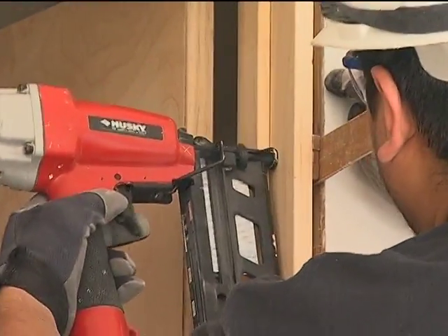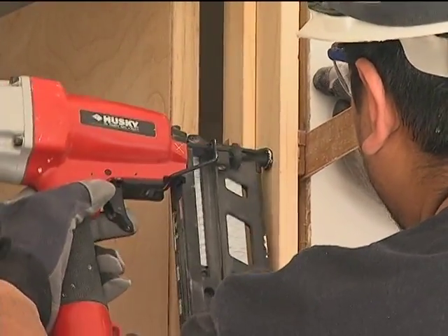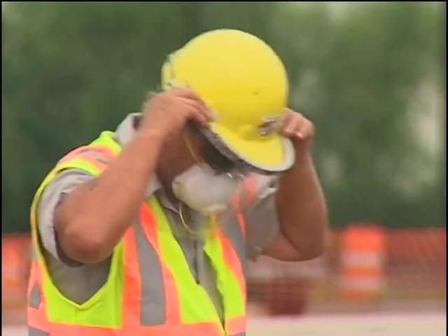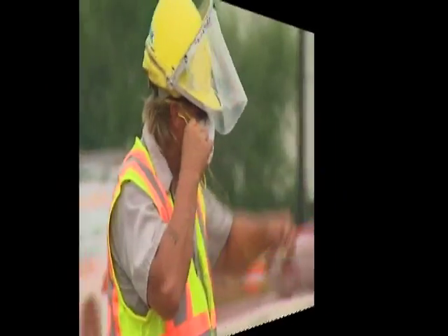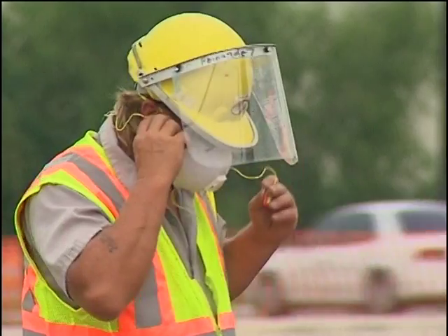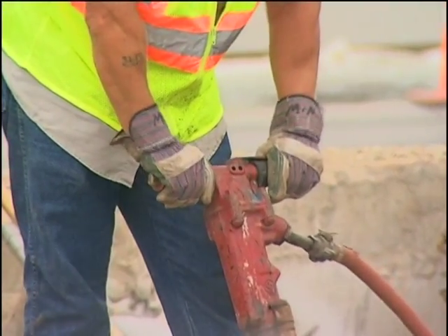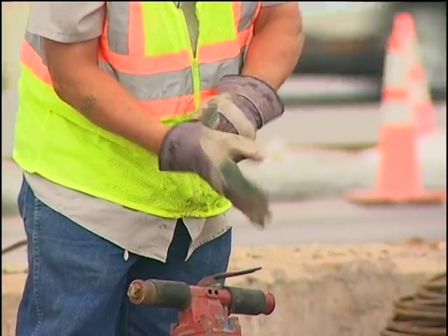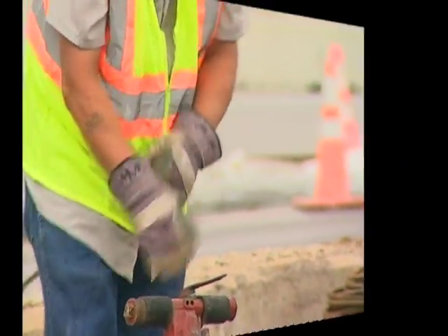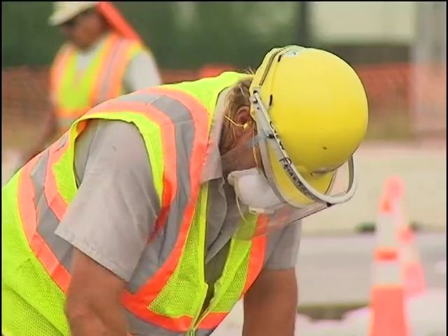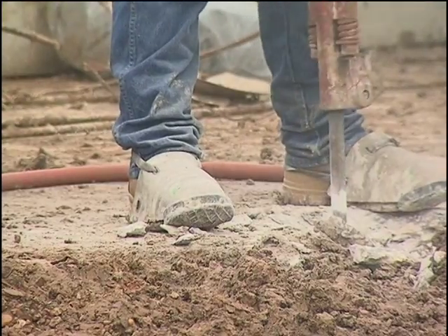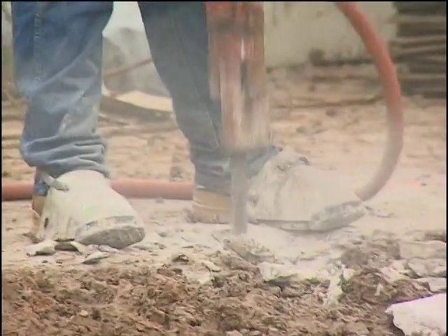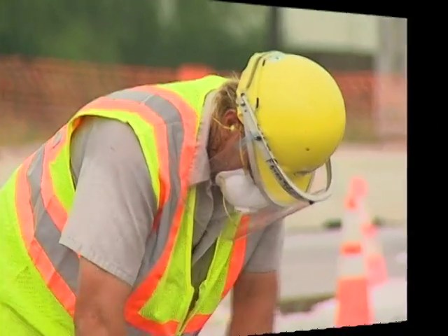When working with pneumatic tools, eye protection is required. Head and face protection is strongly recommended. And hearing protection is required if working with loud, noisy tools such as jackhammers. When using a jackhammer, heavy rubber grips will reduce fatigue and strains. Operators should also wear safety glasses, safety shoes, metatarsal guards, hearing protection, and a face shield.